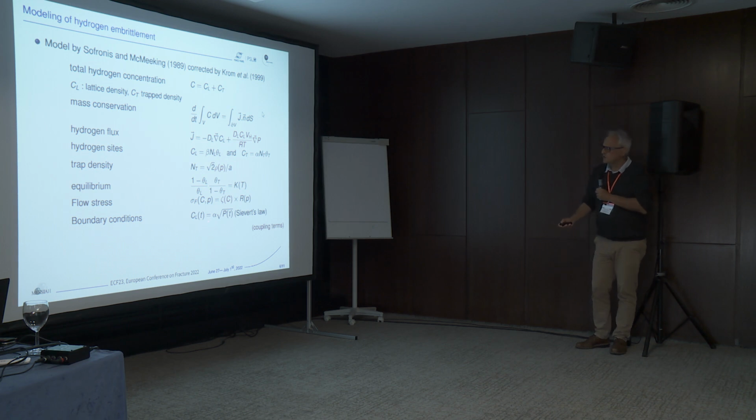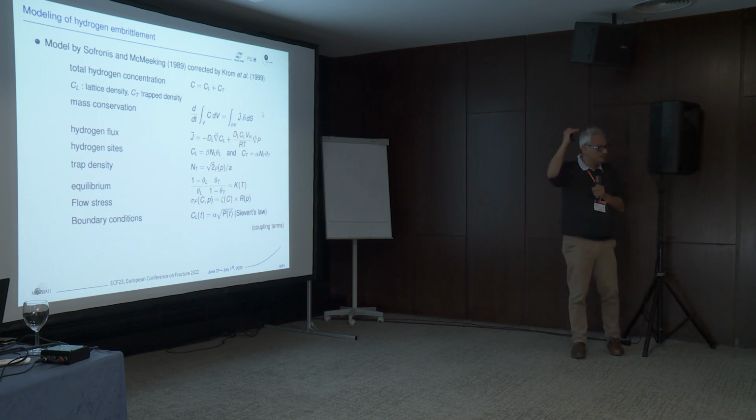Boundary condition, so we apply a boundary condition on the pressurized side by imposing the lattice concentration following the Sievert's law, where P is a function of time because we gradually increase the pressure.